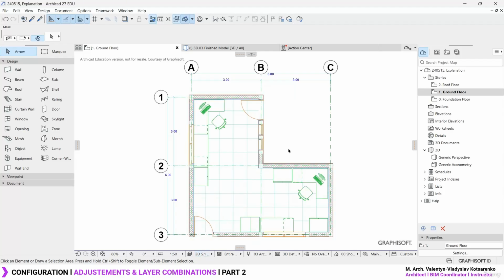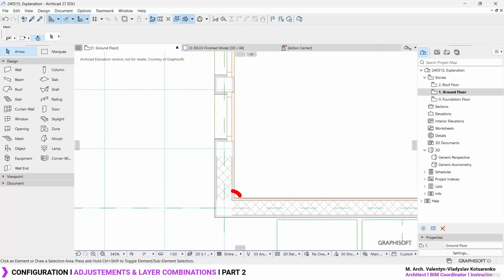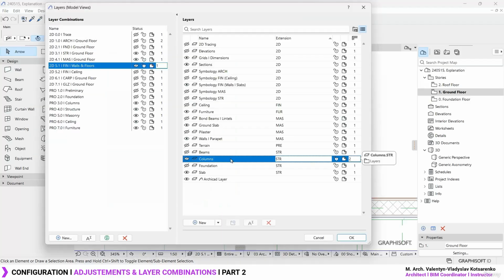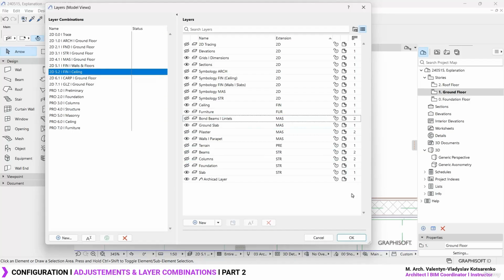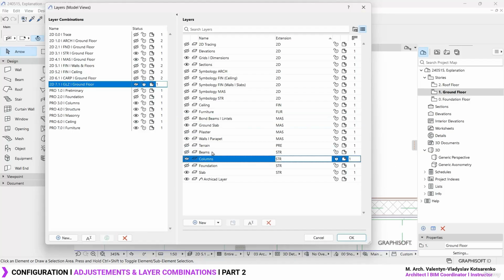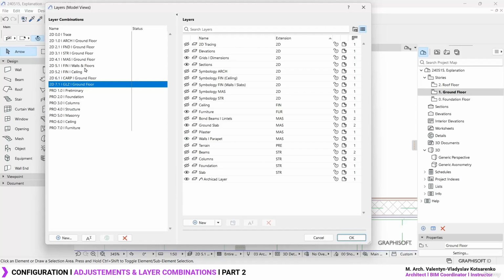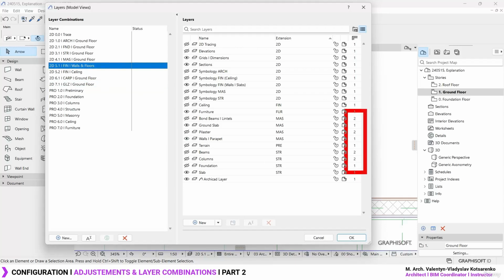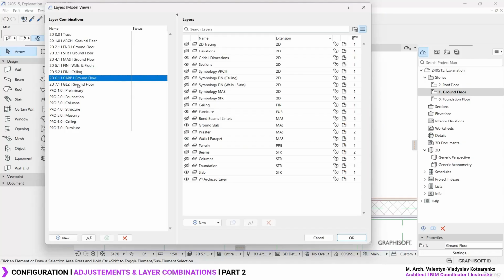Then we've got the finishes. For the finishes, the same thing: you need to specify the intersections. So just select your layers and make sure to set the intersection to a different number. So yeah, pretty much I just made sure that the numbers are different for the elements causing trouble, especially in finishes, carpentry and glazing.